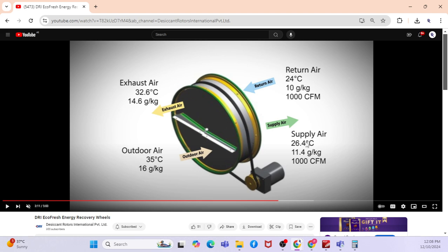After that, what will happen? This supply air will pass through the coil for dehumidification purpose. Then at that time it will go to, say for example, 11 degrees, 12 degrees. Okay, fine. So that 11 or 12 degrees only will be supplied to the space after the sensible wheel. This is just to explain what the condition is. Say for example, if I increase the heat wheel width, then the condition will change. If I reduce or increase the diameter, this will change.